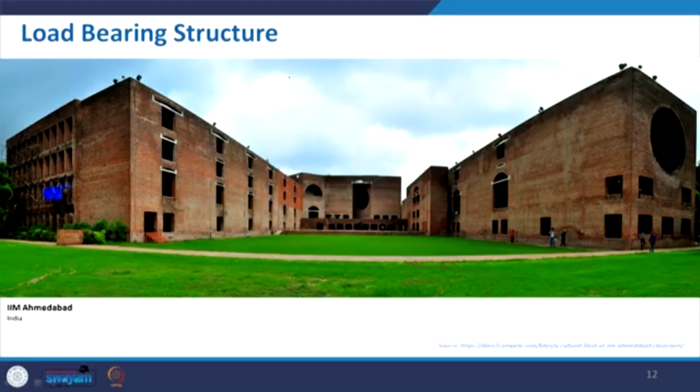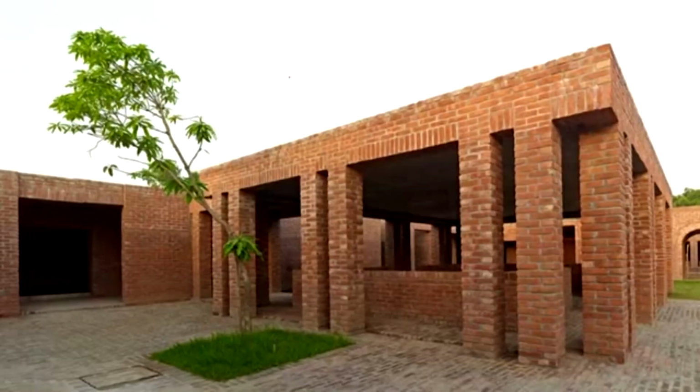This is something modern. This is another arrangement where even the top of this particular structure also has some brickwork. So, this is again a load bearing structure along with the wall. We can also create columns or pillars made of brick. It is also possible to make this structure where all the loads will be transferred to the wall, to the foundation. So, walls and brick pillars are responsible for transferring the load.